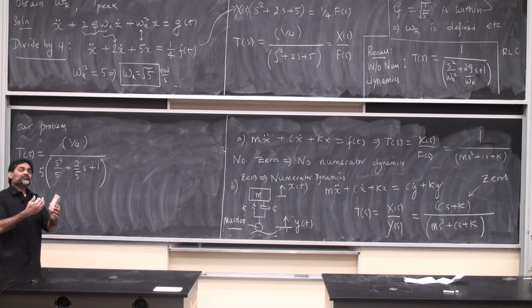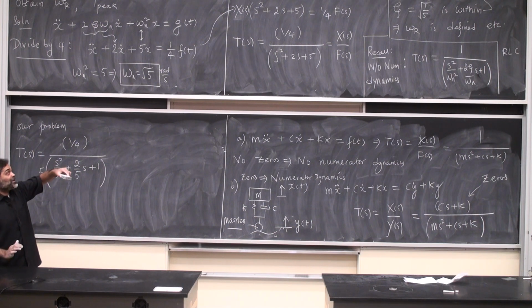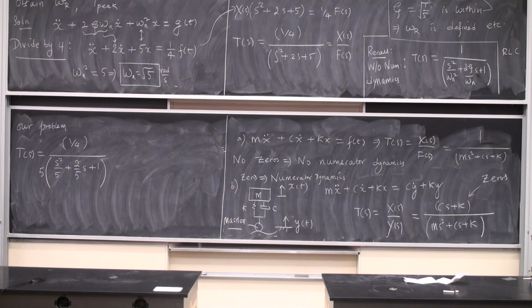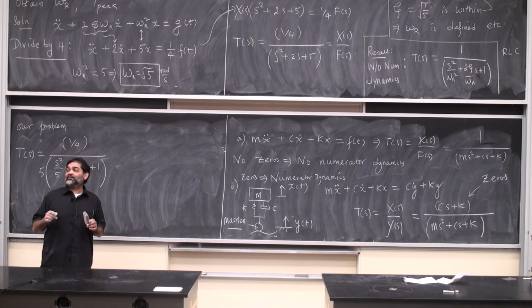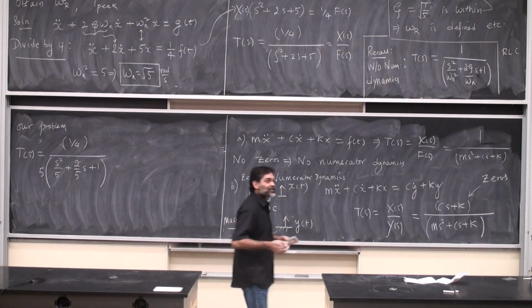If you're doing a first order system, that's what we have done, the RC circuit. So that's going to have a time constant, tau. If you're doing a second order system, it's going to have a damping ratio, a natural frequency, and for a certain range of the damping ratio, you will have a resonant frequency. If it is anything else, what should I do? I should tell you to perform the differentiation again and calculate the resonant frequency and calculate the peak. And since we have done it in class, please expect to be asked that. That's the reason I'm doing it.